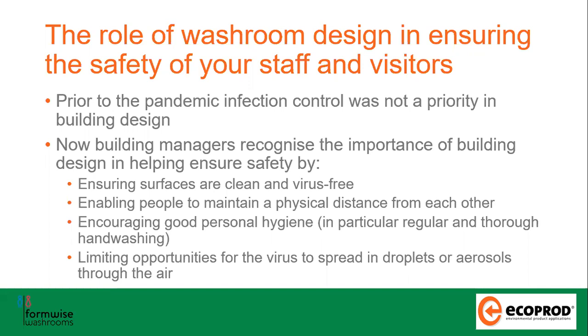The other thing to consider when looking at toilet areas is maybe having a staggered lobby, because it's all well and good people washing their hands, drying their hands, it's all touch-free, and then unfortunately they have to go and open a door to a toilet area, which people don't like. Now, you can get away with that by making the doors push on exit and pull on entrance, but it's just worth considering. If there's room for a staggered lobby, then it's probably worth looking at.